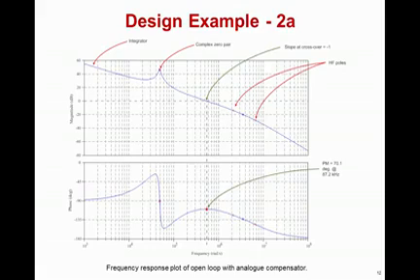You can see that the high frequency poles located in the compensator are out to the right as far as higher frequencies are concerned. This allows you to move the phase lead that we initially saw in the plant over to a point lower, as you can see in the phase graph. This will give you the desired phase margin and gain margin that you're looking for in the open loop of the plant and compensator.